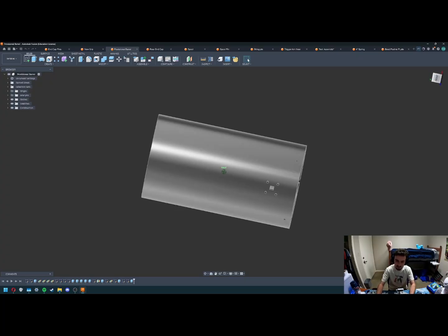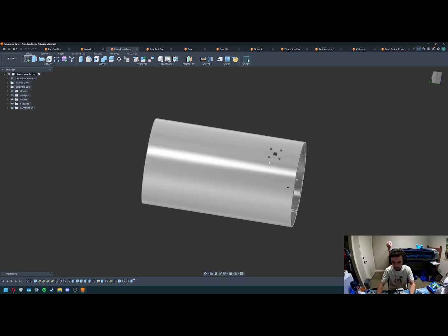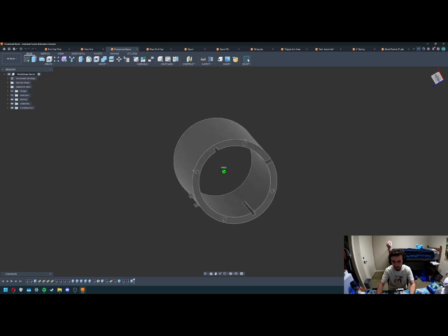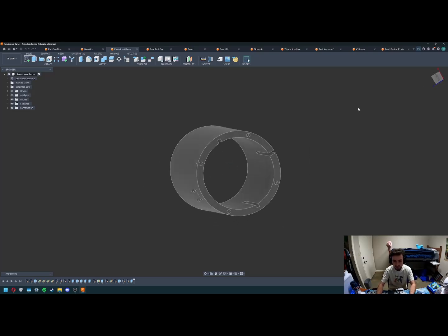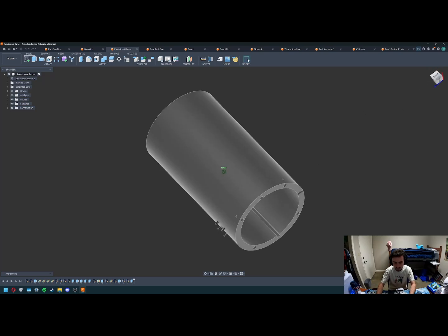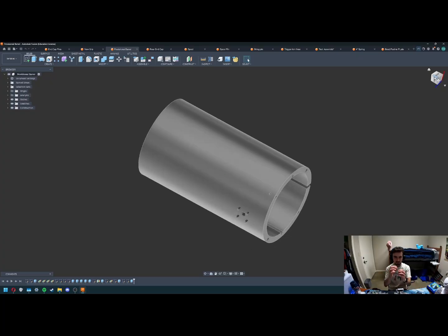And then at the bottom here, we have four little pegs that would help you align the grip, and then this is where the pin would go through that holds back the bead pusher plate, and then the end plate is what the spring pushes on to push the bead pusher plate forward, and it slots in through these four circles here. And to make sure it isn't forced out on the back, we have pins right here that would lock it in place.